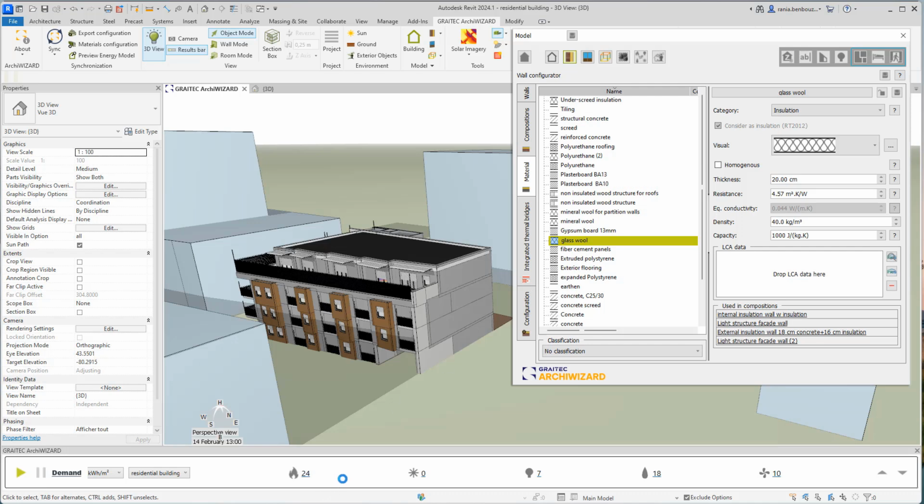So it is calculated. I've seen that I have reduced the heating demand by 1 kilowatt hour per square meter by raising the thickness by 10 centimeters. I would conclude that gaining a kilowatt hour per square meter for 10 extra centimeters is not that cost effective, as I already had a good insulation. So this simulation helps you, for example, take decisions on your insulation level.